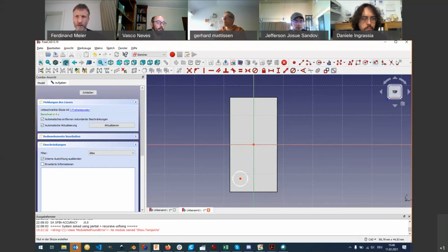It's a blue cube with a line extracted. So I select this one. In my case, it's in this drop-down menu, but I hope you'll find it. And I select this one, and then I click on the left edge of my cube.